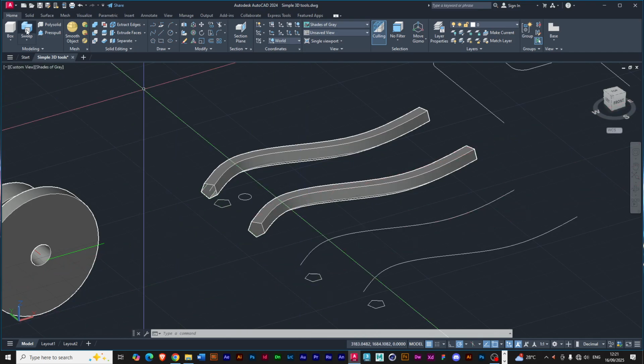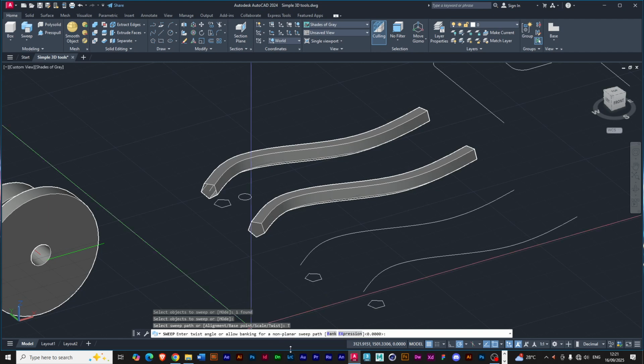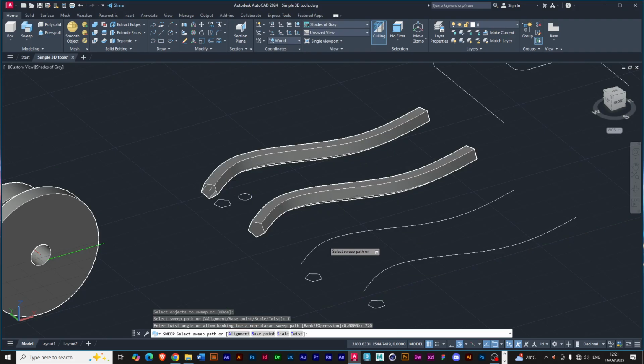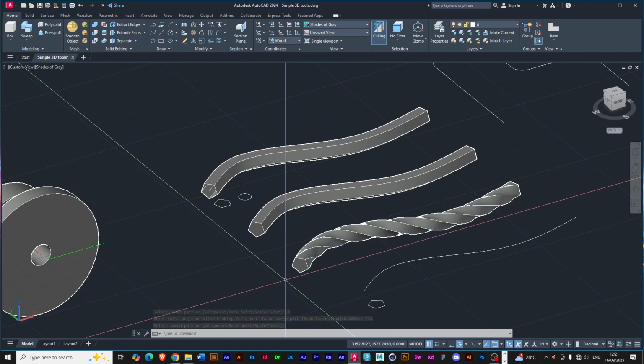So I was saying the other one we did, let's say I've said the surface. If we did scale before, let's say I do twist, and my expression, let's say I wanted to twist 360 degrees two times, like 720. Yeah, that's 720, and twist this guy, create that twist. Because that's 360 degrees twice, it's like the profile is twisted.